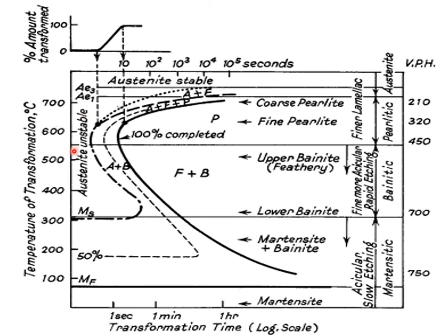So if we want to achieve bainite, what we'll do is take a temperature below 550, above 500, and then hold it for a very small amount of time, and then suddenly cool it. So we'll be getting an upper bainite, and similarly we'll be getting a lower bainite if we cool it from this region around 300 to 400.